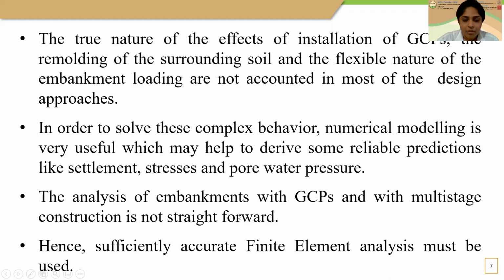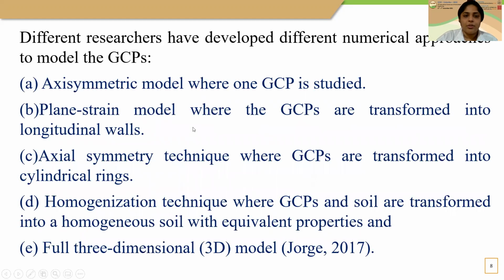Also, in embankment construction, the embankments are constructed as multi-stage construction. This will further make the situation complex. Therefore, it is very important that we have a sufficiently accurate finite element analysis to study the settlement variation, the pore pressure variation, and how the stresses are going to vary in GCP improved soft ground. Here you can see the studies done by past researchers, who have developed various numerical analysis models.